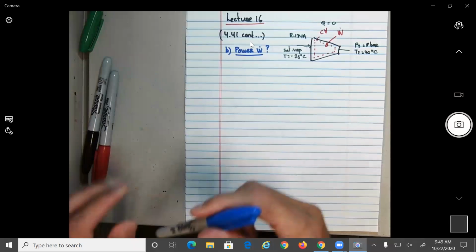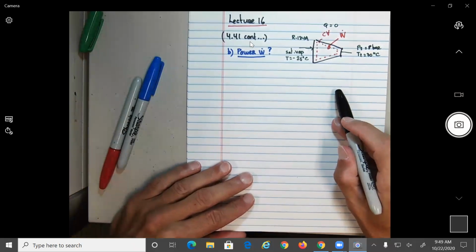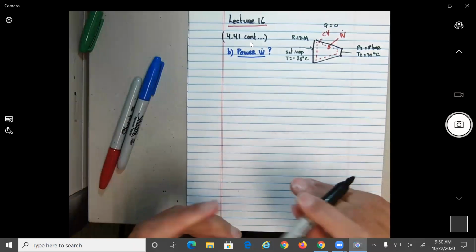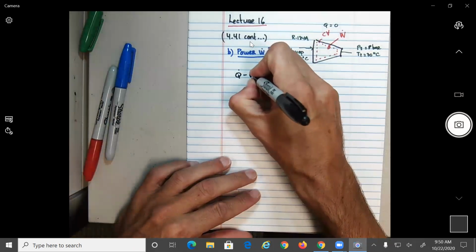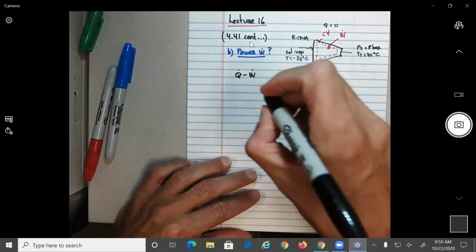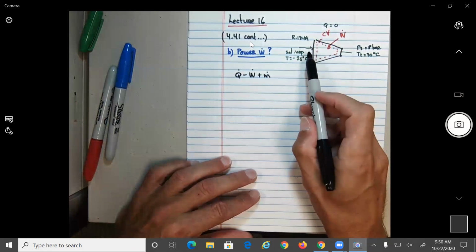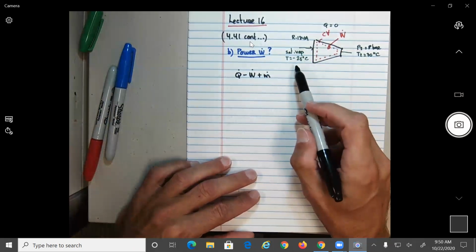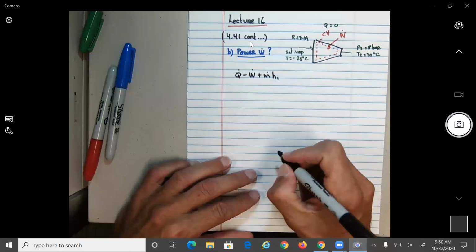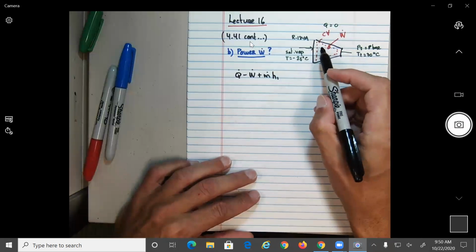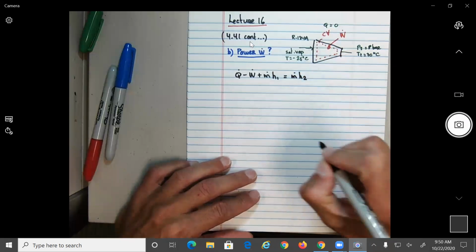Okay. So what do we need to do over here? What type of system is this? This is a control volume system. So we need to apply the first law of thermodynamics for a control volume system, which will be what? Q dot minus power, plus m dot, the mass flow. We know the conservation of mass flow is steady state, so m1 equals m2. We did that on the previous problem. So it will be m dot. What is coming in? h1. Then we neglect kinetic and potential energy, and what will be coming out? m dot h2.